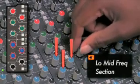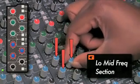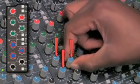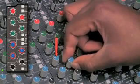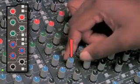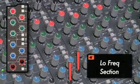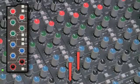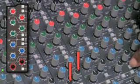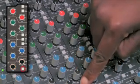Below this is the low-mid frequency band. Similar to the high-mid frequency band, we have gain, boost and cut, Q control, and frequency selection. Finally, we have our low frequency band, with your low frequency boost and cut, and frequency selection. Same as the high frequency, we have the option for a shelf or fixed Q bell curve.